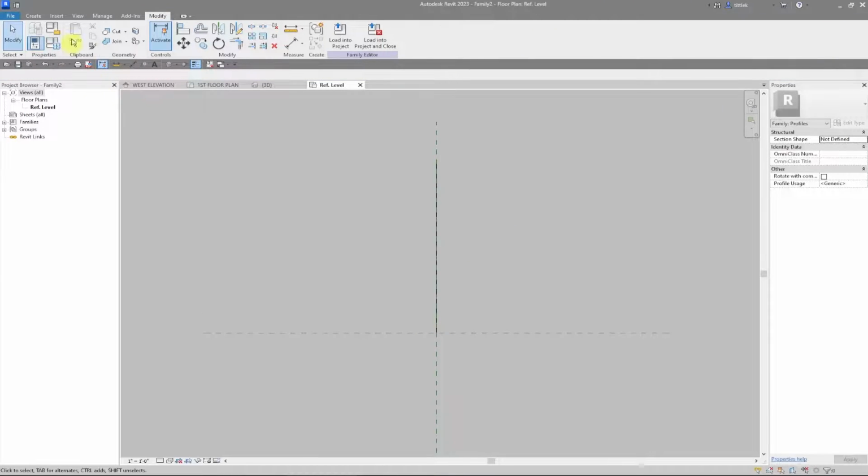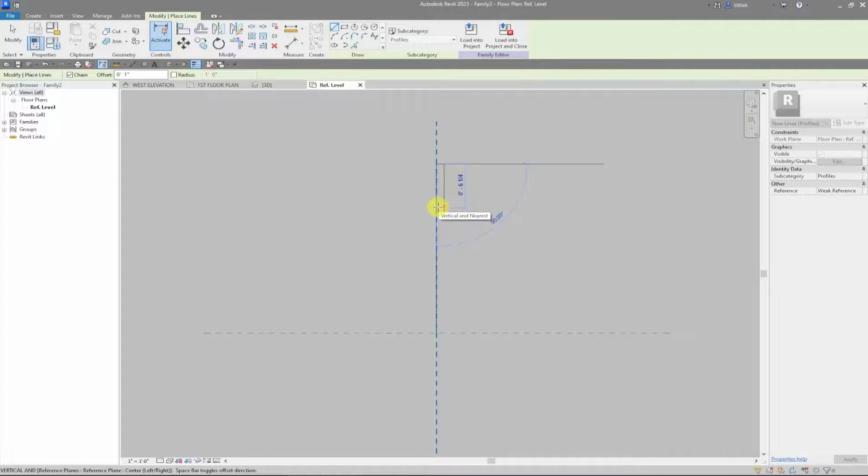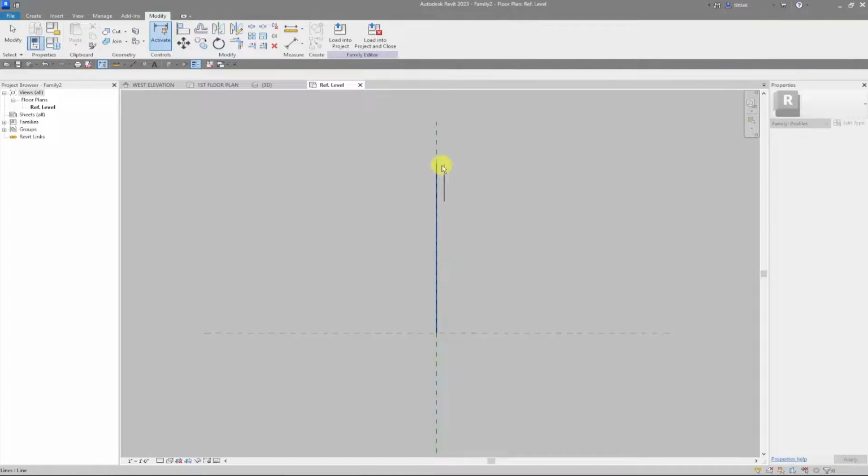Bottom of this, so I'm going to go back to the create line tool. I want a line at the top here, 1 inch. So I have a 1 inch overhang of my sill to the exterior. So that's easy enough. I can choose the line and I can do the offset, and I'll do 1 inch. And I'm going to trace this line down 5 and 11/32 of an inch. Now that's, for all intents and purposes, 2 brick courses in height, rounded to the closest 32nd of an inch.